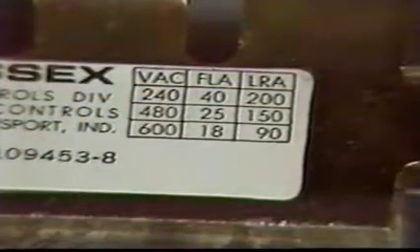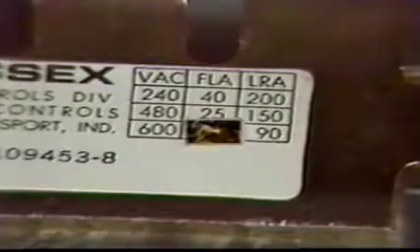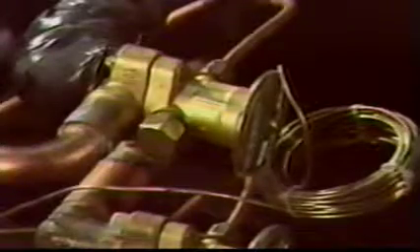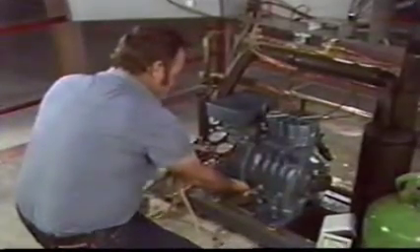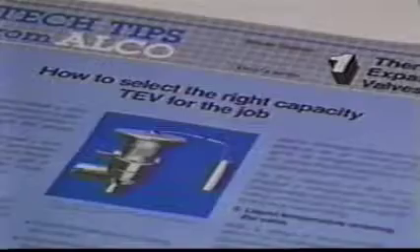Fortunately for most components, the conditions in the real world are very close to those used in their rating. For many other components, such as compressors and expansion valves, things are a little more complicated. Their performance depends very much on the conditions under which they operate. For expansion valves in particular, the size selection must go beyond nominal ratings. The service technician or designer must look at all factors that will affect the true capacity of his valve selection. There is a price for doing otherwise.